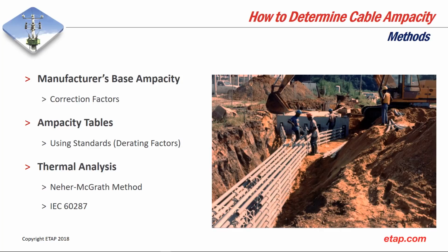Also the ampacity tables using standards and derating factors. This is more for NEC and ICEA P54440 standard, where the standard typically provides us with ampacity tables, also with installation tables, so we can go there and look it up. Also, and this is not part of this presentation, thermal analysis using the Neher-McGrath method or IEC 60287 can also be performed to come up with a thermal analysis to squeeze the most performance out of our cable installations.